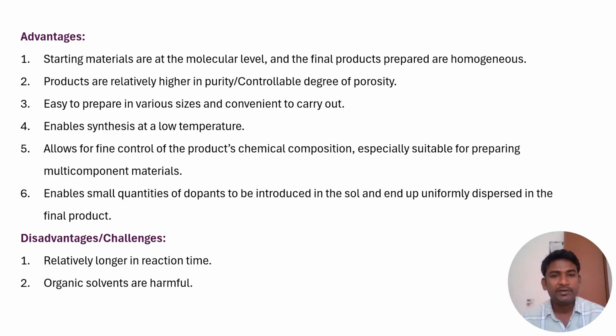Advantages: starting materials are at the molecular level and the final products prepared are homogeneous. Products are relatively higher in purity and we can control the degree of porosity. Easy to prepare in various sizes and convenient to carry out. It enables synthesis at low temperature. It also allows for fine control of the product's chemical composition, especially suitable for preparing multi-component materials. It enables small quantities of dopant to be introduced in the gel and end up uniformly dispersed in the final product. And finally, the limitations, that is disadvantages.